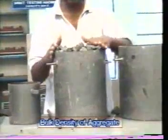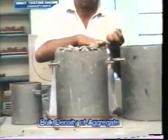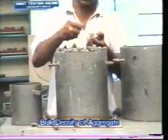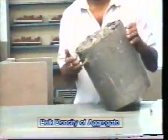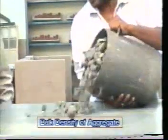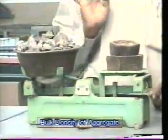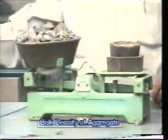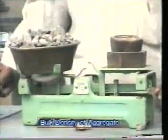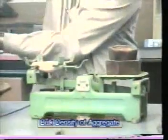After filling, level the surface of the filled measure neatly, flush with the sides of the measure. Now weigh the sample of the aggregate filled in the measure and report the bulk density of aggregate as weight of sample of aggregates in the measure divided by its volume.